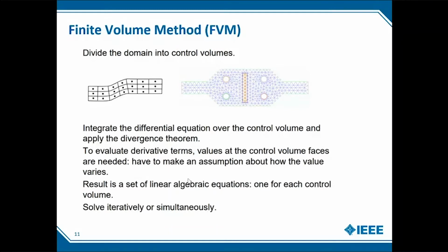Now that was the basics of the finite difference method, which is a good start to solving CFD problems. But all the software that you have heard of, let it be Ansys Fluent or OpenFOAM or any other fluid flow software, uses finite volume method discretization and not finite difference method. The main reason is that if you have a complicated geometry, like the right-hand side geometry over here, it's literally impossible to solve it via finite difference method, or you'll have a very complicated code to solve that. That is why the finite volume method performs much better on this geometry.